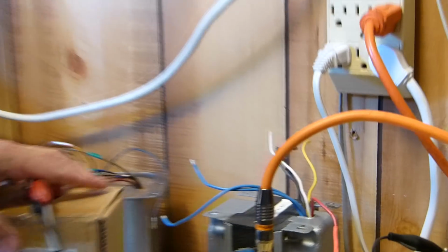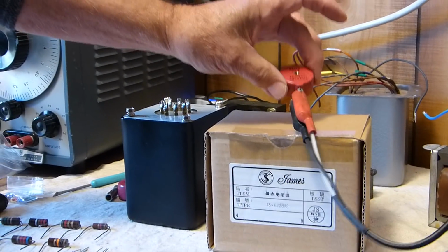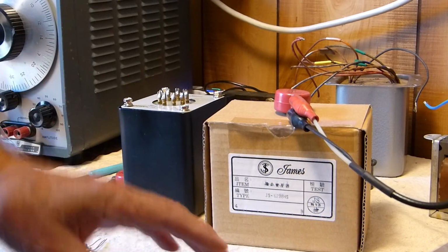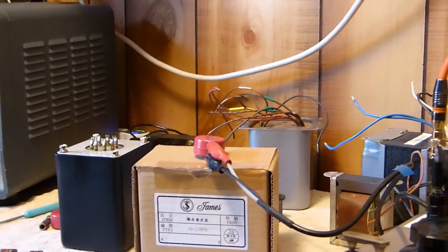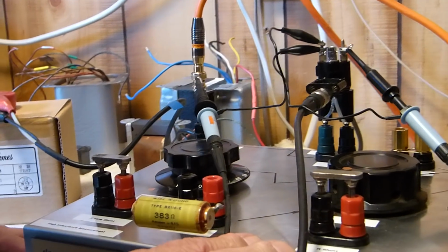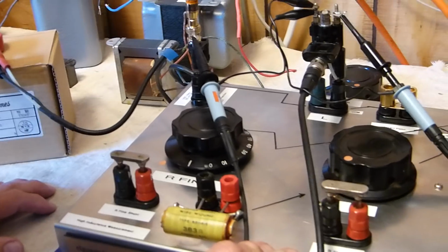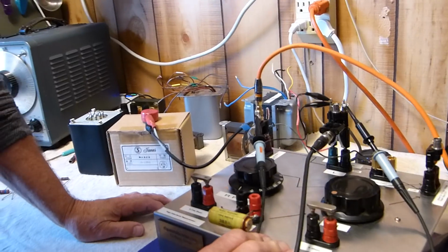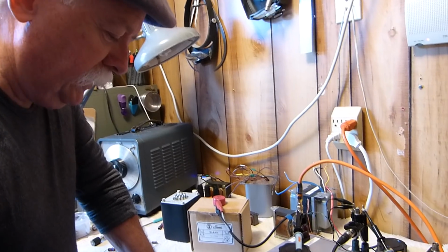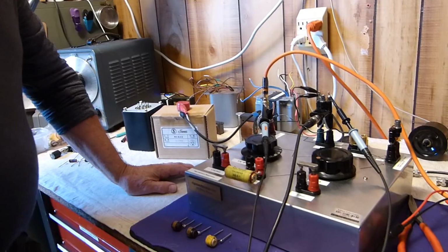Okay. Also, I've noticed that you need to set it up on something and not get any kind of interfering noise source next to it, like a fluorescent lamp. I'll show you that in just a minute too. So if you want to make one of these setups so that you can measure inductance, you've actually got to make yourself some sort of a legitimate test jig, because if you just run wires and clip leads like I did in the beginning with alligator clips on both ends, you end up with a very unpredictable setup, and you won't get the same answers twice.